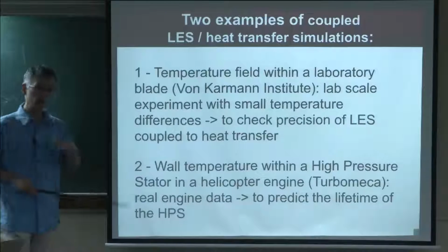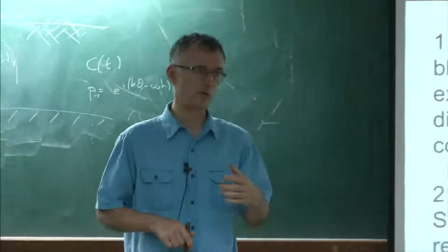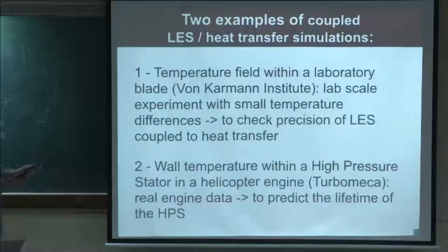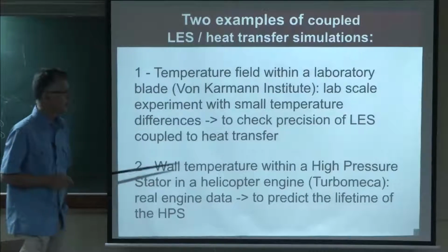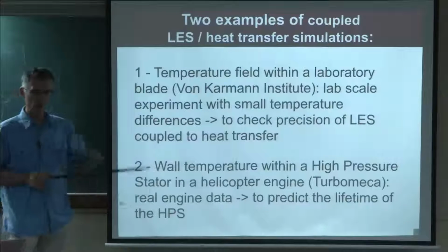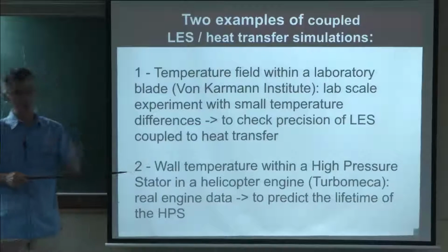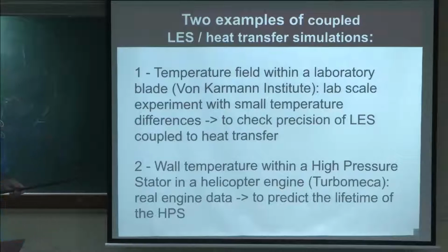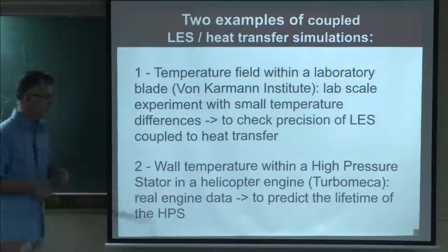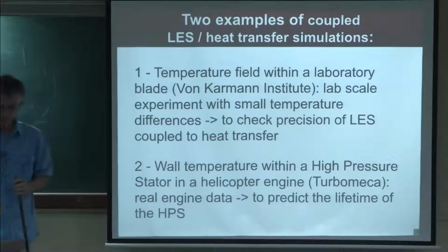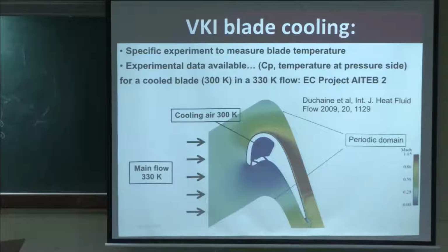One of them is what you need to do first before you do an engine. You need to do academic cases, and those cases come from the von Karman Institute, where they did a lab-scale experiment with small temperature differences to check that you can compute the heat transfer with LES on the blade, for example. And then I will show you a helicopter case from Turbomeca with radiation to show you you can do it also in a real configuration.